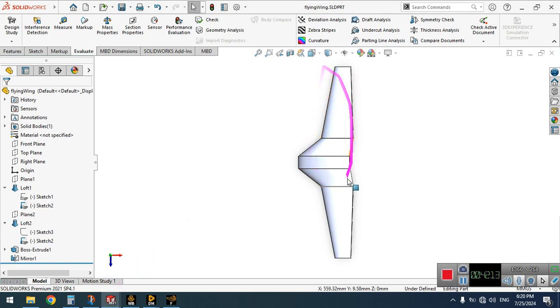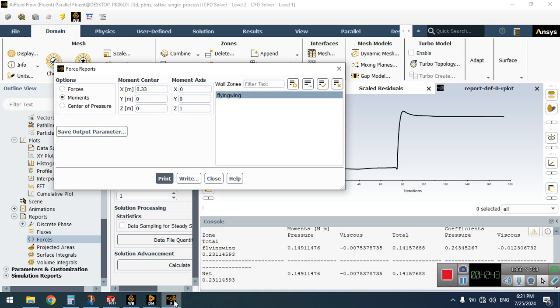So you should arrange your components inside the fuselage so that your center of mass gets to 35 centimeters, about 2 centimeters behind the proposed neutral point, somewhere here, for example. To make your flying wing stable during flight, it is very important. If you have any other questions about this simulation and estimation, just let me know. I would be happy to help.